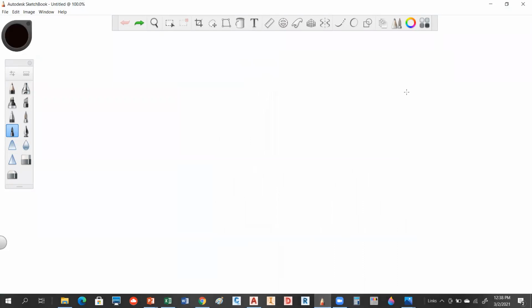When we get out into the lab, what I'm going to have everybody do is set up at a specific point. We've got 4 groups in the one lab. I'll just give you a point, let's say, for instance, I'll put a stake in the ground. We'll say you're going to set up at this point. This is where your instrument will be. From that point, we're going to measure out a distance of 75 feet, and you're going to do that with the EDM. You want to get that at exactly 75 feet, and we'll put in another stake.